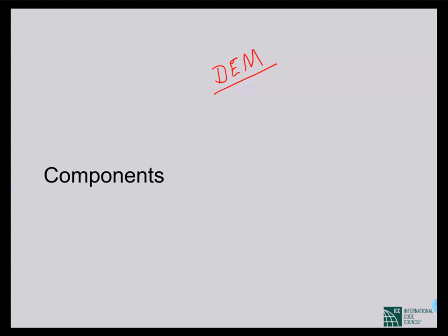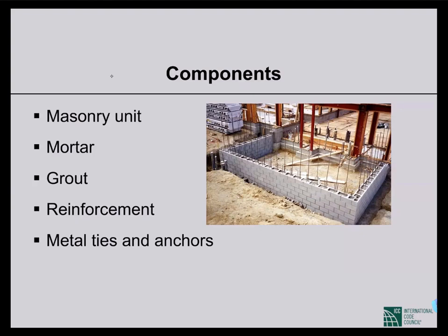Any analytical software to analyze masonry structure? Have already answered these. What is the difference between WSD and ASD? In working stress design, in WSD, what do we calculate? We calculate allowable working stresses. We don't calculate the ultimate capacity. We always calculate allowable working stresses.